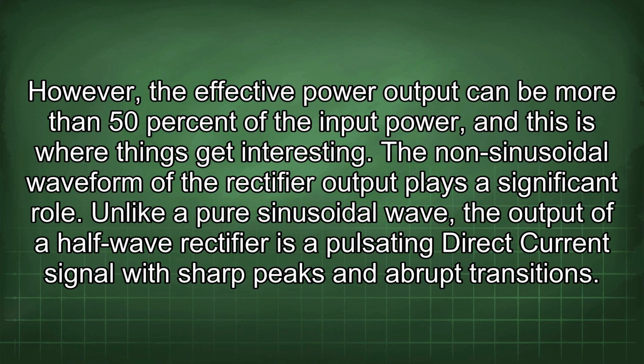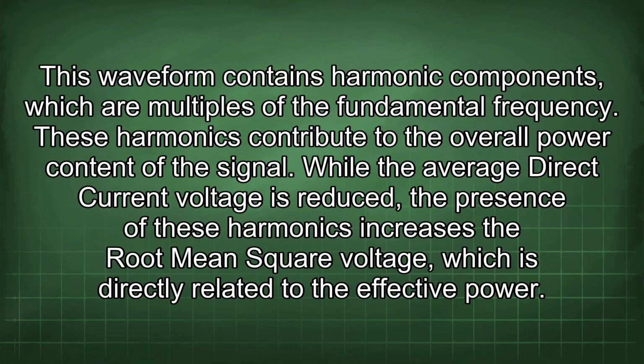interesting. The non-sinusoidal waveform of the rectifier output plays a significant role. Unlike a pure sinusoidal wave, the output of a half-wave rectifier is a pulsating direct current signal with sharp peaks and abrupt transitions. This waveform contains harmonic components, which are multiples of the fundamental frequency. These harmonics contribute to the overall power content of the signal. While the average direct current voltage is reduced, the presence of these harmonics increases the root mean square voltage, which is directly related to the effective power.